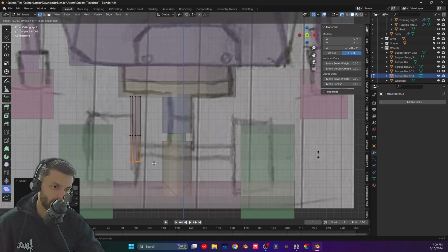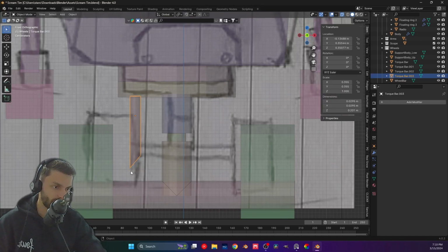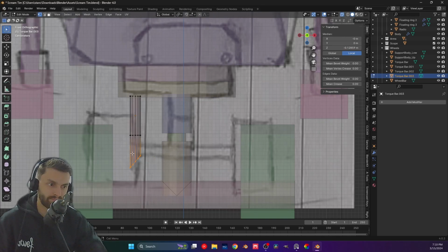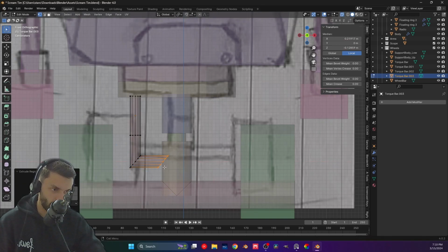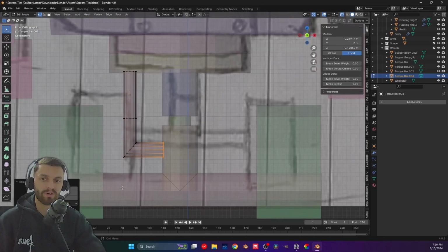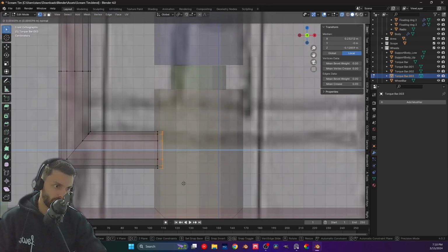Everything is more or less gonna be copied, at least in some shape or form, right? Because, I mean, it's the way things go. So let's actually get this maybe kind of around here. Does that work? I think it does. And with this selected again, let's press E, X, and this will go all the way here. Now S, X, 0, and now it's straight. And we have this corner. It's a little trick that I like to use to get those sharp corners.